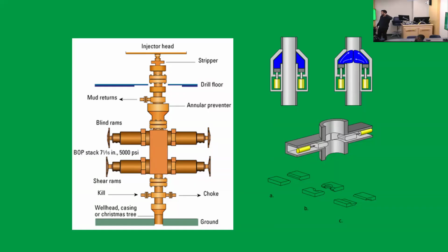In fact, if you do have a kick getting into the drill string, you will need to either pump down and get it out from the annulus, or you can also do reverse circulation, but it's a long story. Reverse circulation is possible. You can inject from the annulus and get it out from the drill pipe. It's not impossible to do. We were doing exercises like that about reverse circulation when I was in Texas. But most likely it's going to be in the annulus.